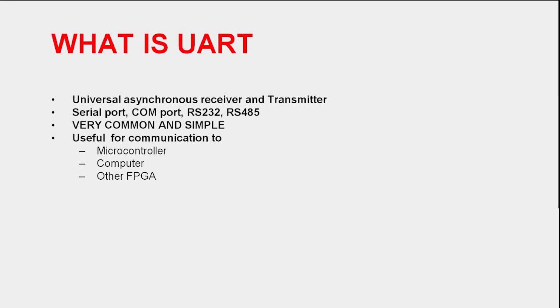Generally it is not used to connect multiple devices. It is used only for two-way communication between 2 devices. When you try to connect multiple devices on the same bus, you may get a bus contention issue on UART, when multiple devices try to drive the bus at the same time. So if you want to communicate between only 2 devices, then UART is the best communication platform.